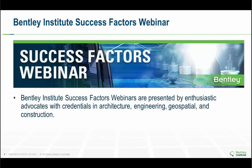Yes, Alan. I would also add that, beyond the direct analysis method, there are other approaches to include the residual stresses directly in the iterative analysis, but those analysis computations are very expensive. I'm sure that's in the way the material is defined, or the right number of properties are defined and then used in the finite element analysis.